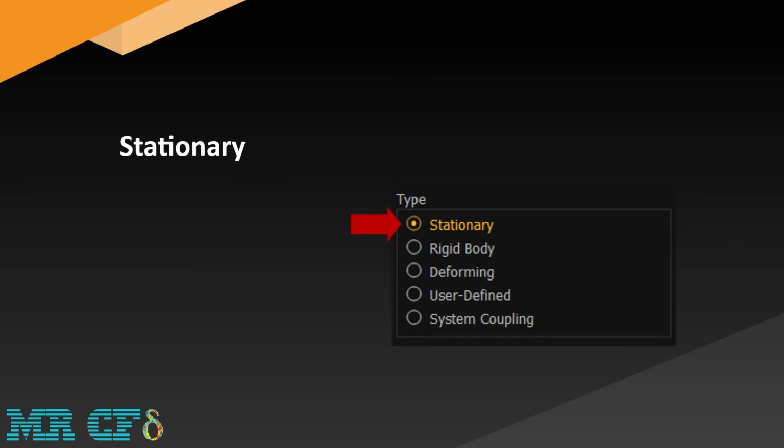If the dynamic area is stationary, we have to use a stationary model, so that in static mode, the mesh nodes of this area are excluded when updating the location of the nodes. In other words, mesh update is not applied to them. By default, if no motion, whether deforming or moving, is assigned to a cell or contact area, that area is not considered in the mesh update to the next time step.